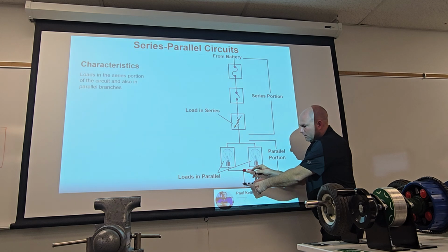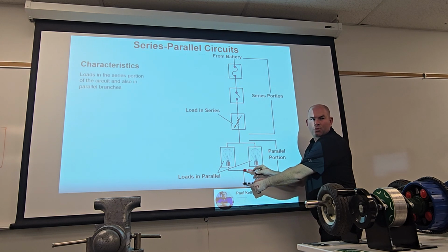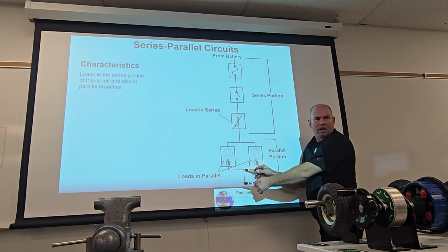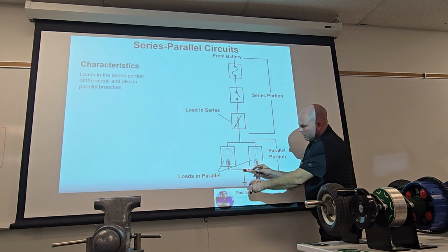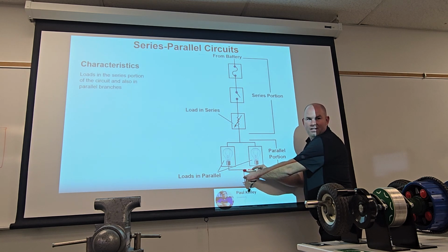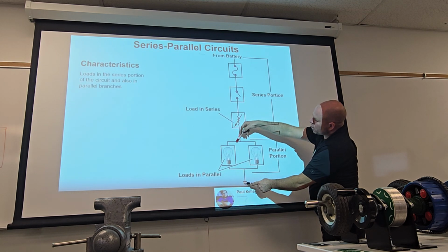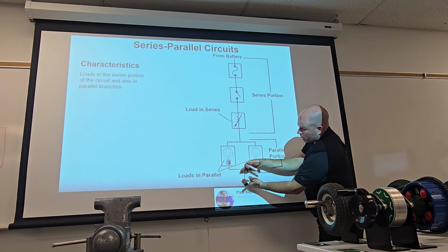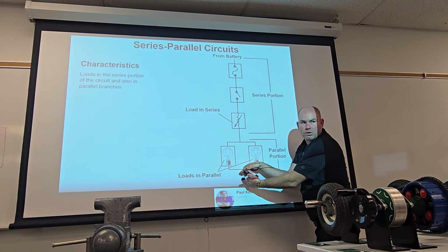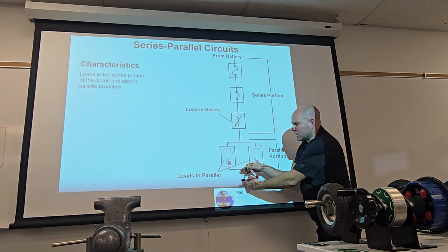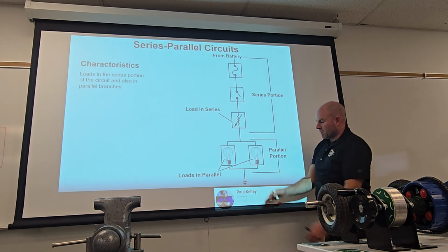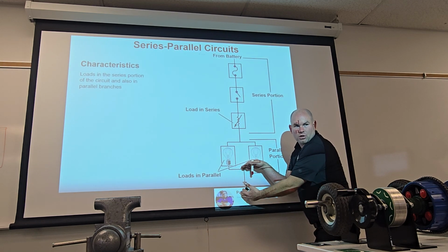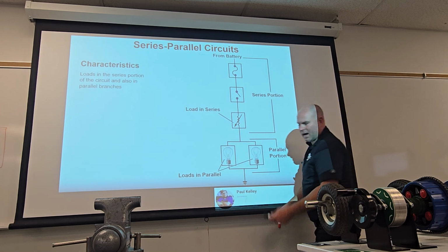All bad. The bulb wouldn't be bad if it had 12 down here. Oh, did you say all bad or bulb bad? If I have 12 volts after the load, you know what that tells me? There's an open down here on the ground. The only reason 12 volts will go through the load is if there's a bigger, much more infinitely strong resistance down here, right? These two twins are like, well, we'll only take 0.1 because there's something with like a million bajillion ohms down here. Make sense?